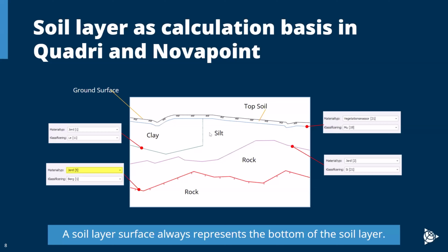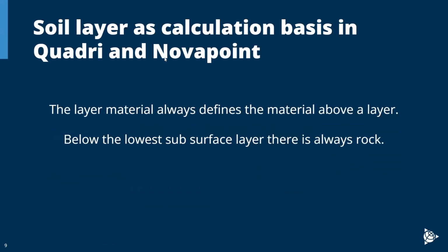So what's really important to remember when working with subsurfaces in Quadri is that all the Novapoint modules interpret the area below the lowest layer to always be rock. We're going to get back to that several times, but that's really important to remember.